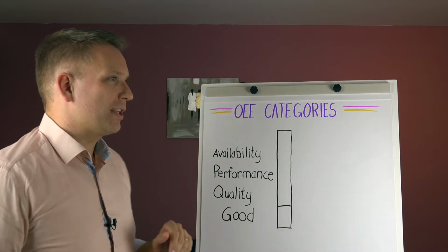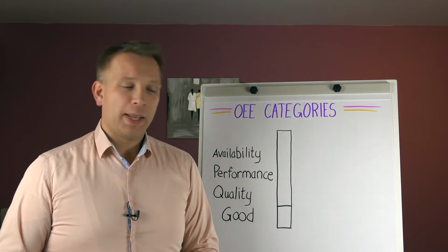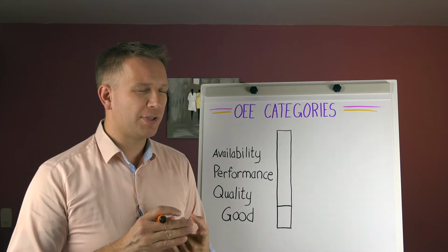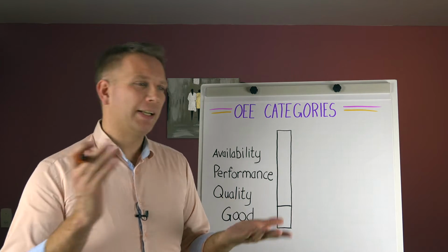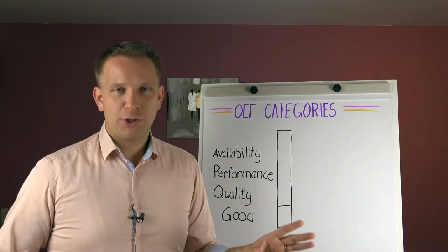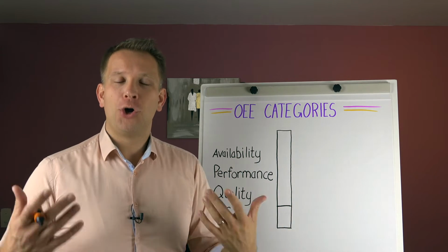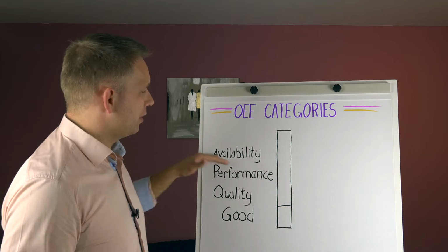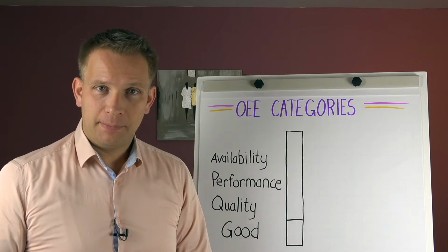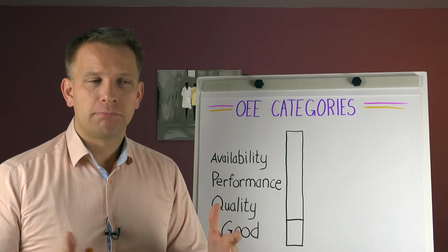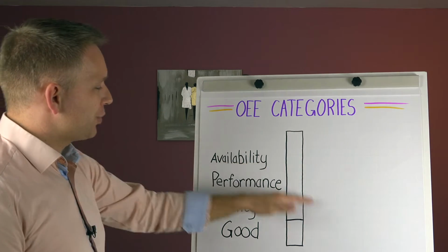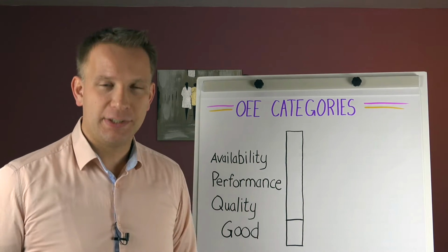And the availability losses, they are a huge category, because they are, the factory is closed, which is usually completely left out of this type of OEE registration, but also do we have some plant maintenance, or are we cleaning, and even do we have a breakdown. So everything that just completely stops the line so that the operator cannot operate that line, that is all an availability loss. As soon as the operator is actually working with the line and they're producing product, maybe fast, maybe slow, maybe good, maybe defect, that is all in that part where the machine is available.